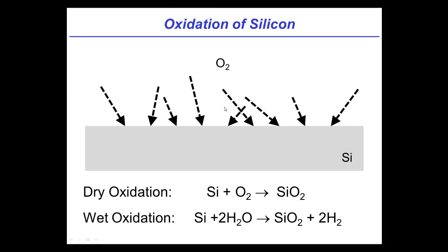The oxygen interacts with the silicon, and it starts forming silicon dioxide. Now, if you think about this, this is kind of interesting. What's happening is the oxygen is actually eating away some of the silicon and consuming it to form SiO2. Oh, that's right, because it grabs an Si and O2, put it together, makes SiO2. Correct. You're left with that, and some of the Si, of course, went into the SiO2. Right. So what happens is the effective remaining thickness of Si gets smaller as the thickness of SiO2 gets larger.